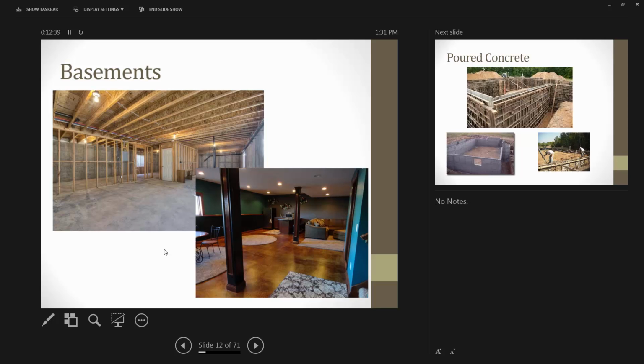The basement itself is in contact with the ground, so it's always conducting directly into the ground. Certainly recognize that basements are usually cooler, which is great in the summertime, not so good in the wintertime. It's because of that direct conductivity with the ground. And understanding once you get about 5 to 6 feet below the surface, you have a fairly constant ground temperature, depending on where you are, what part of the country. Here it's about 54, 55 degrees.